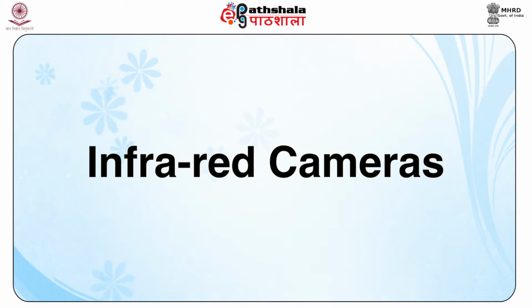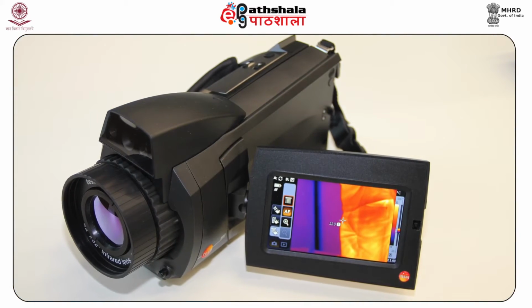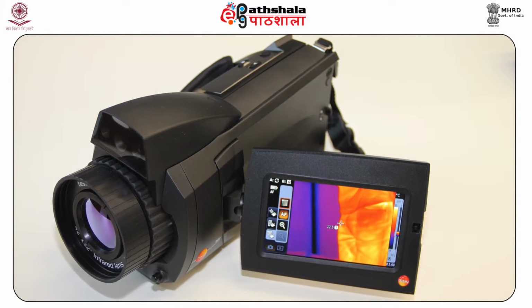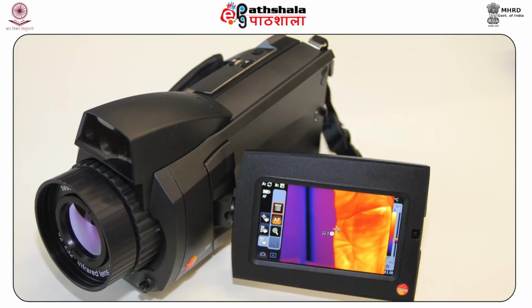Third is infrared cameras. The distance that infrared cameras have the capacity to see is based upon their illumination. These cameras have LEDs which reach out into the darkness. Realistically, a good rule of thumb is 1 foot for each LED. Therefore, if a camera has 30 LEDs, then it probably can see about 30 feet.